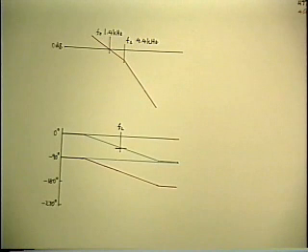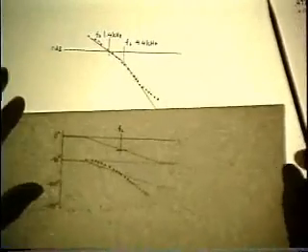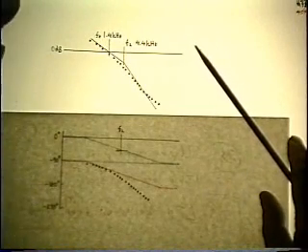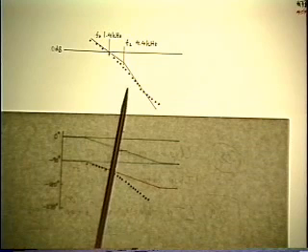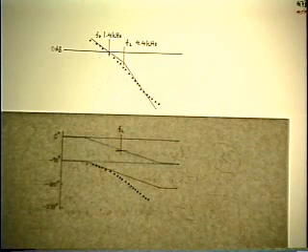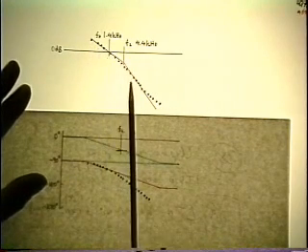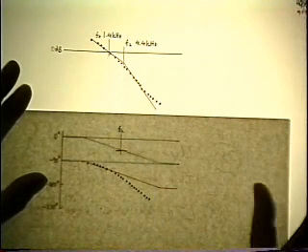So we make measurements using one of these techniques, and what we find is this. And this is typical. Some of the measurements agree with the prediction and some of them don't. So what we've done is confirm the magnitude of the loop gain at low frequencies, and it follows the corner of the second pole, and then we get a deviation at higher frequencies.